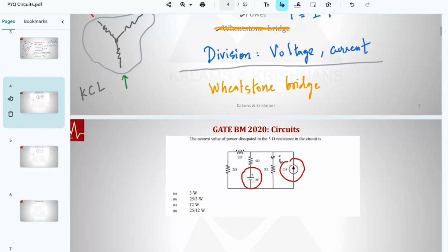Convert voltage source. See, there are two sources, and can you deal with them? Can you make them similar sources? Source transformation. If you do source transformation, perhaps things get easier. And can you simplify the circuit to as few resistances as possible? Again, you are doing a source transformation. Girish is saying, can you do nodal analysis?